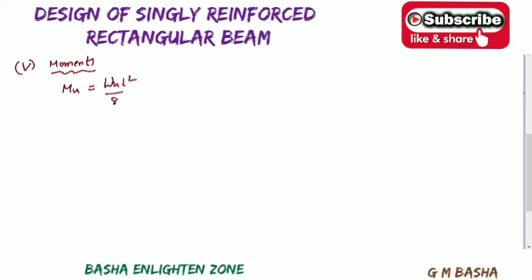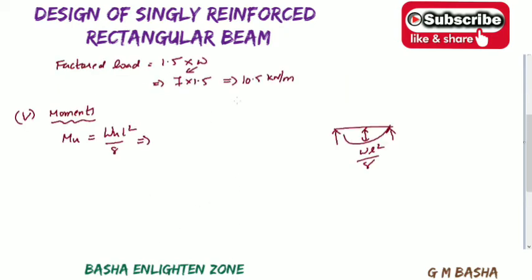We know that the maximum bending moment for a simply supported beam is wl square by 8. Already we know that. So based on this, we can consider w, which we already simplified in the previous step, that is 10.5.